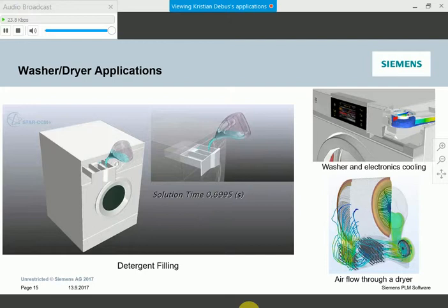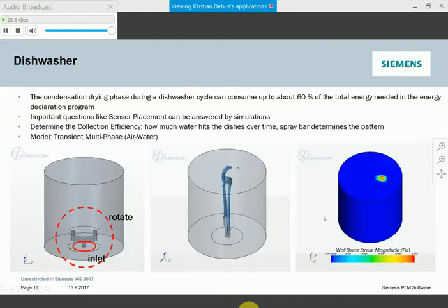And on the bottom, there is a flow-through dryer where we really want to highlight the geometric complexity that we can handle with STAR-CCM+. We modeled completely the flow around this heat exchanger, and even the flow through the fan. In this case, it's actually modeled as a fan completely, not just as a fan curve, which you can do as well. And when it gets into the nitty-gritty, you can see those holes in the drum here, very fine to resolve. So we have specific techniques like a wrapper that you can use to even capture those little details.